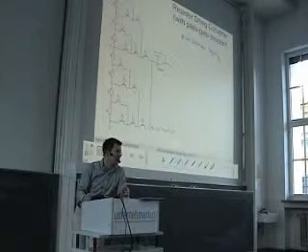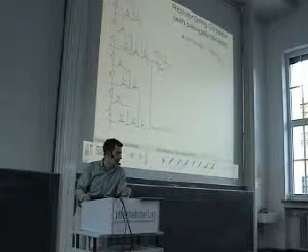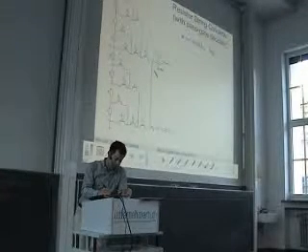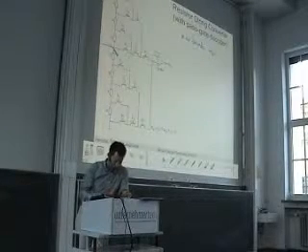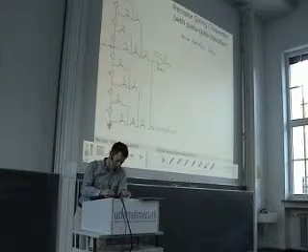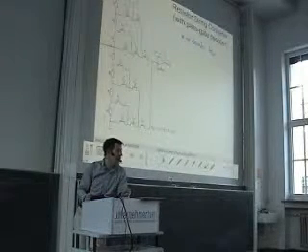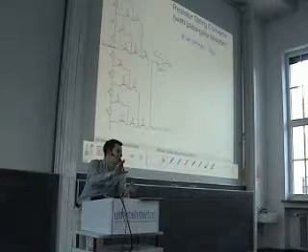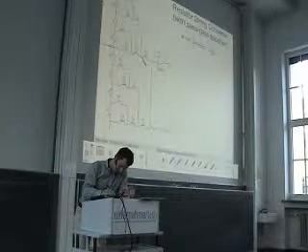Instead, we have now a binary tree of switches which actually acts as a decoder. So let's start with the MSB. You can see we can partition all our voltages in two parts. So we have here all the lower voltages. Here we have all the higher voltages. And we use the MSB to select whether the output voltage is in the upper range or in the lower range. So this is done by these two switches.